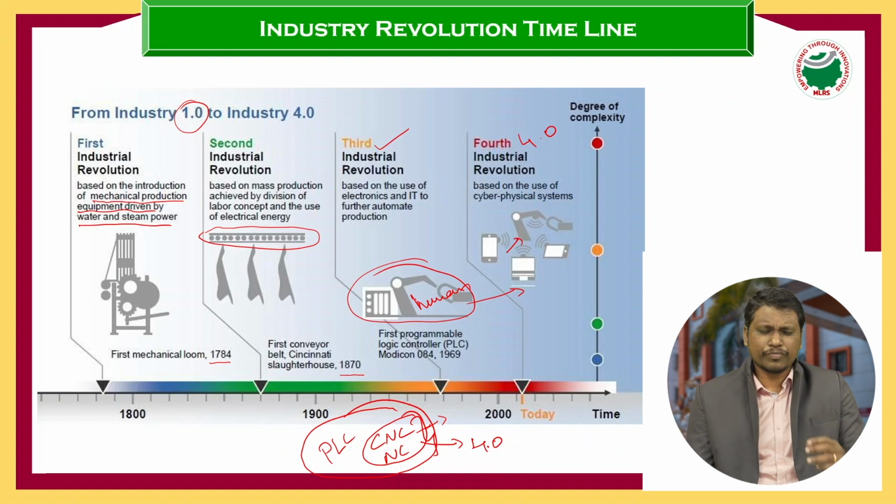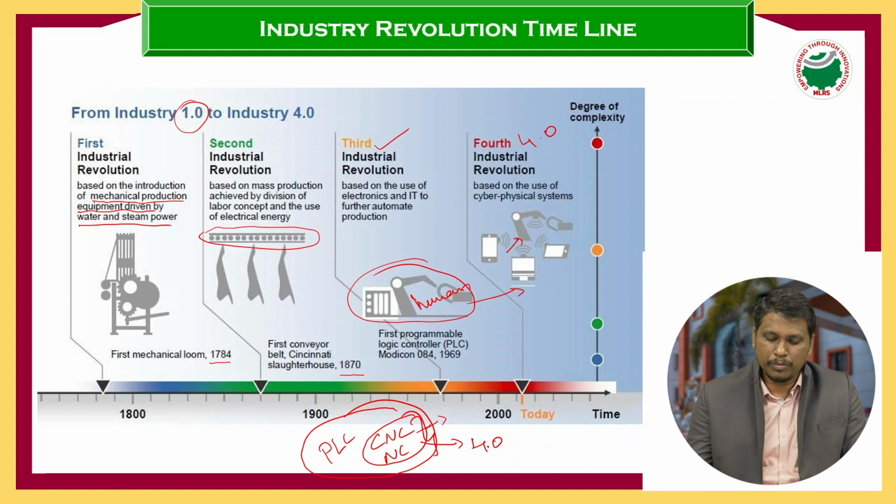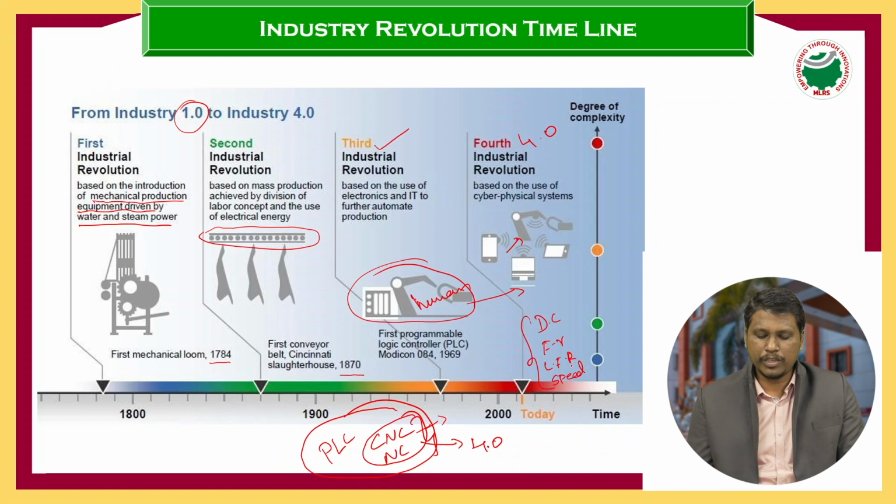In the lathe machine, we have a number of components. If you want to do any machining, like taper turning or any machining process, we have to set some initial parameters on that machine. What are the initial parameters? For example, depth of cut, feed rate, as well as lubricant flow rate. Like that, some initial parameter setup. Again, speed we have to give. These are all important parameters used for running the lathe machine.